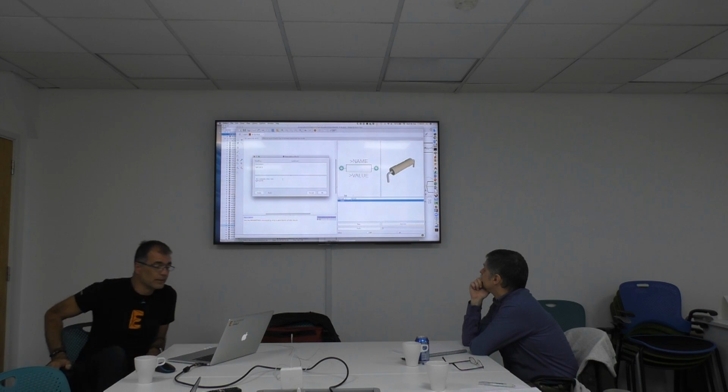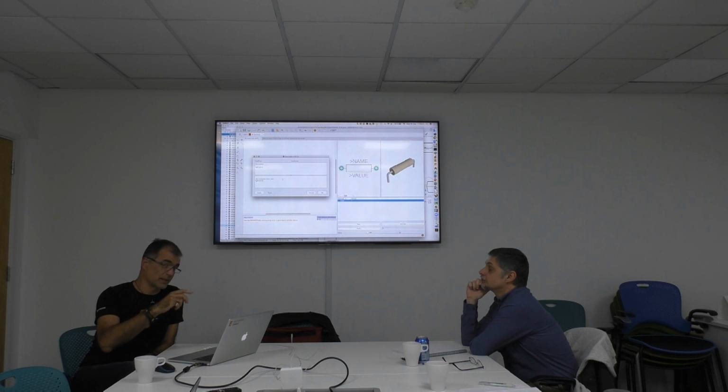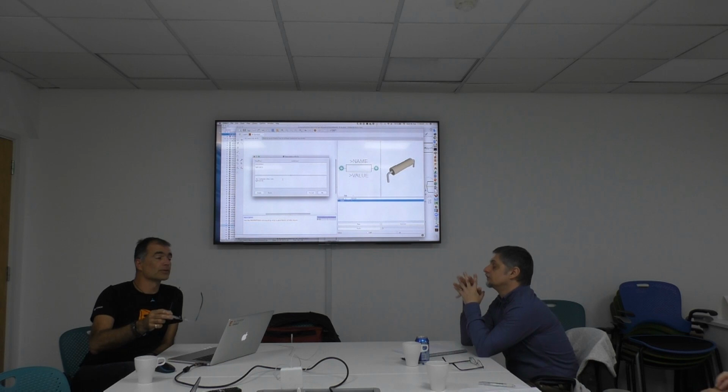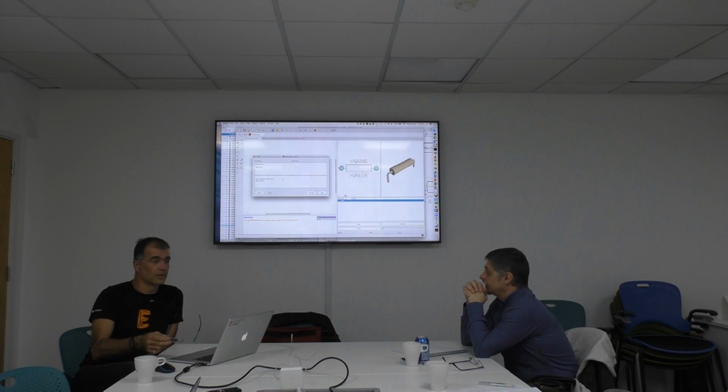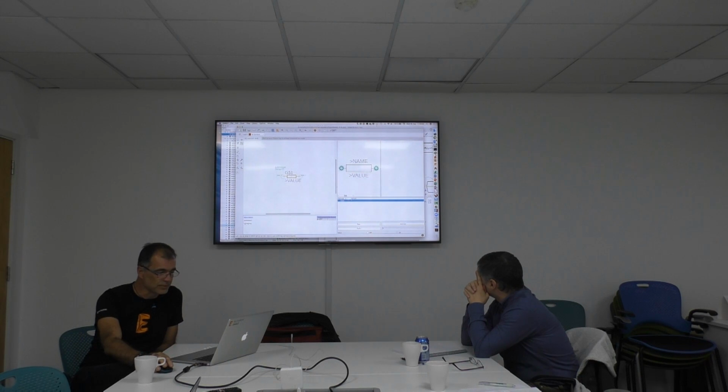It's HTML. So it makes sense to have a good description because in the add dialog, if I search for something, Eagle can also search in the description. So if I do not know what the name of the component is, maybe I know it's a crazy timer, then I search for crazy timer and then I will find it. Something like this. Okay. Good. And then we have technologies and attributes.